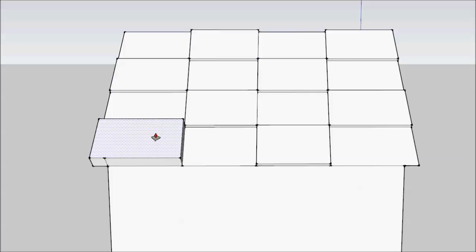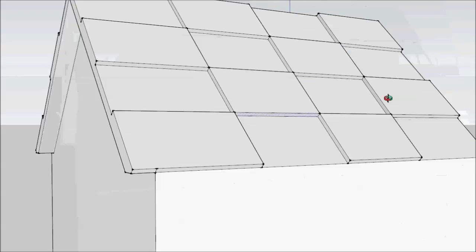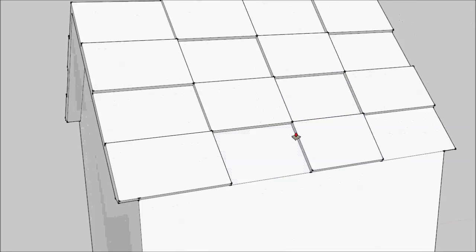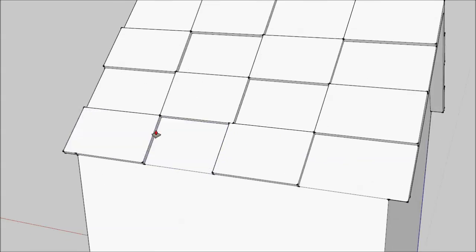The only thing if you do this one is that at these intersections where the tiles hit each other, they're touching, but they're infinitesimally small. There is no thickness, and the computer will freak out at those points. So what you're going to do is you're going to overlap them a little bit by pulling the edges outwards or inwards. It doesn't matter how far you pull it, but they need to be overlapping each other ever so slightly.